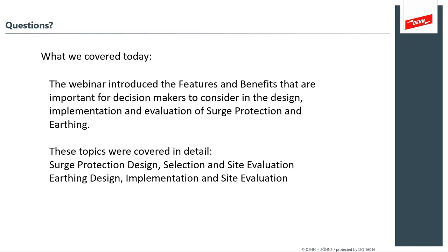So you would, yes. What I wanted to add, Mark, is remember with older installations, way back then we have more robust electronics, and the PCBs and things back then are less electronically driven. So if a client really hasn't had a loss or does not really have a significant risk, I would say you could get away from recommending an SPD for that installation.